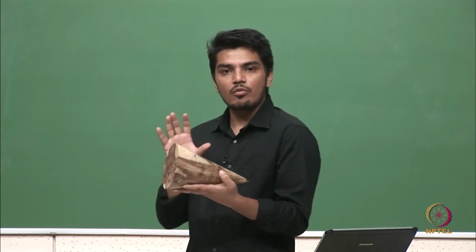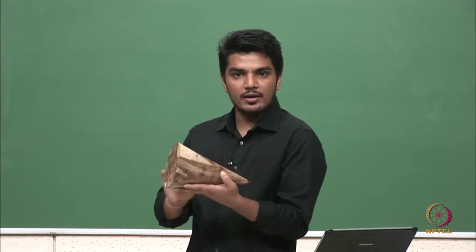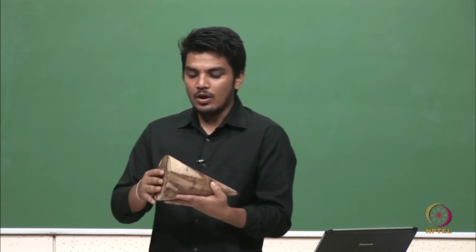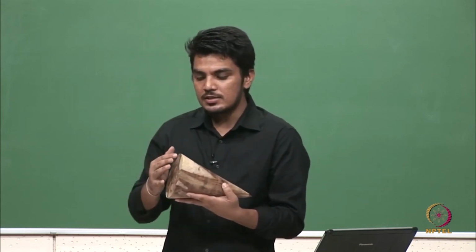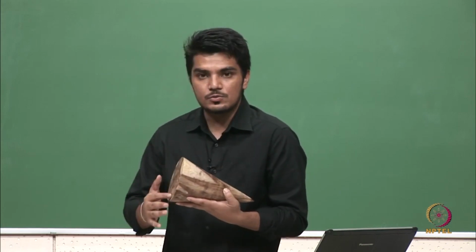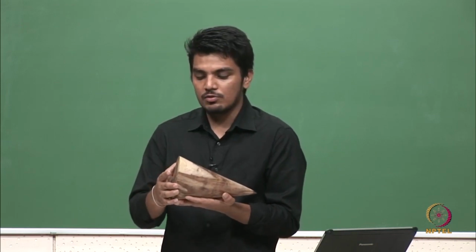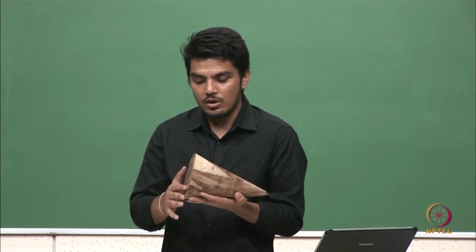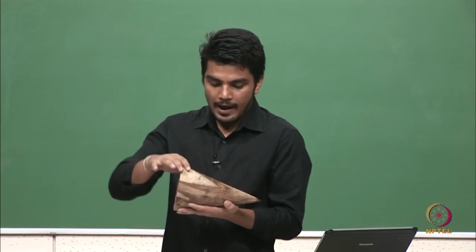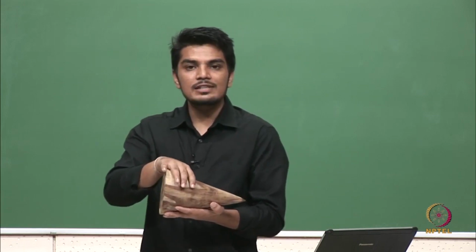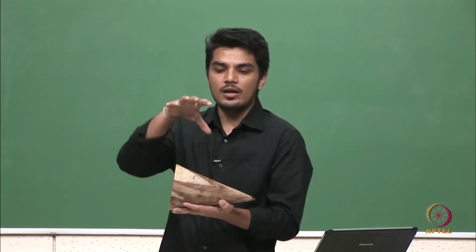Now on seeing from front, we will get the same triangle as obtained in the first orientation, but on seeing from top, since the base of the cone is not parallel to the horizontal plane, we will get an ellipse. Again we can visualize it. On seeing from top, this base of the cone can be seen as an ellipse and its surface can be seen as a triangle. So we will start with front view followed by the top view.